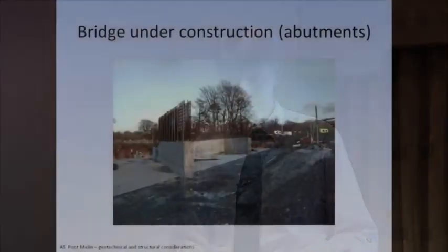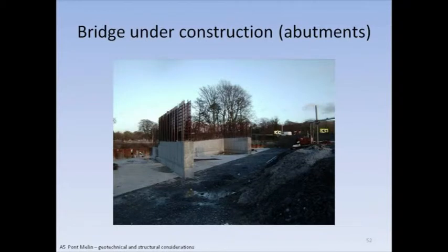But it was completed. The contractor got the base down, and this is the first lift for an abutment. So you can see that it's more than a kicker. It's come up to half the height of the reinforcement cage, such that they could extend the cage to the finished level once settlement had occurred.